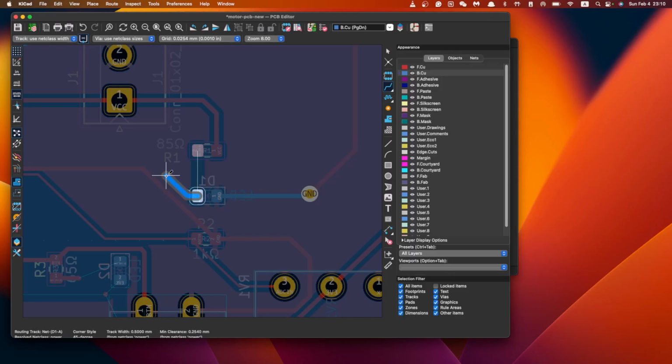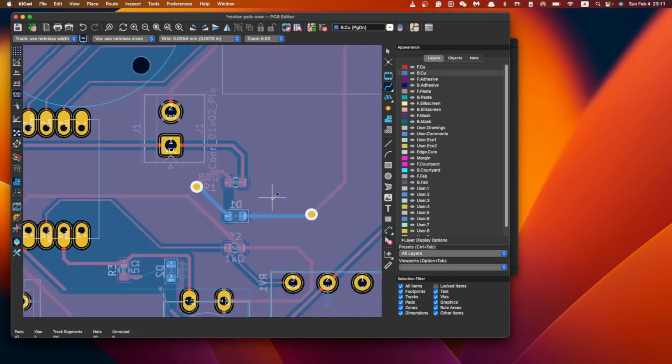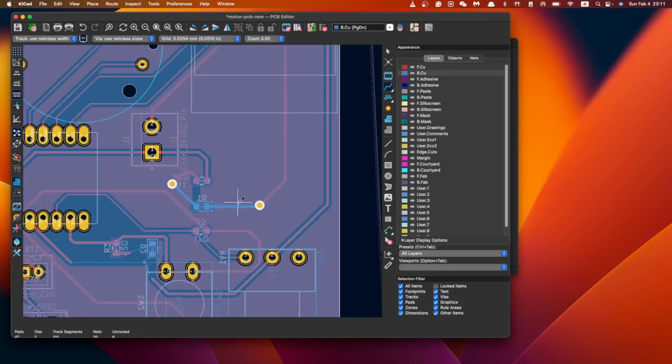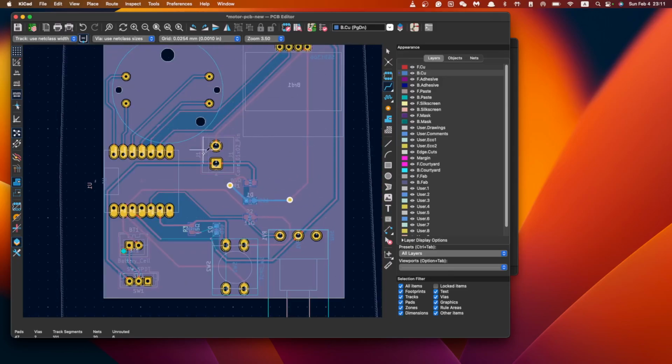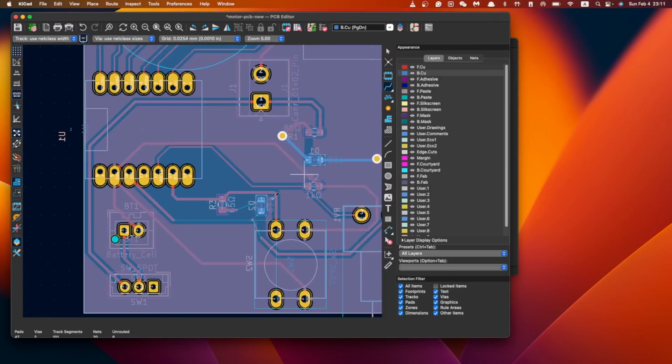And then, since this pad is on the front side of the board, I'm going to connect it like this. So perhaps, okay, and then nice. By using those two vias here, we can connect this LED with the existing circuit pretty easily.